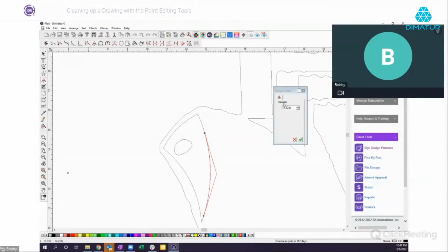And then you can actually define the diameter of the arc. I can make this bigger if I need to, or bring it in. You can see the dot that's over here, so I can kind of control that arc. This is probably not the best example of where to use it, but as you see, it doesn't give you quite the control that the 3-point arc does, okay?